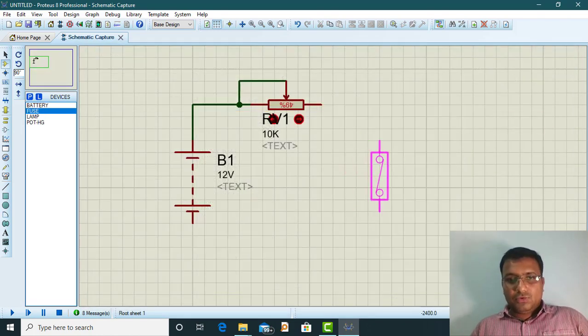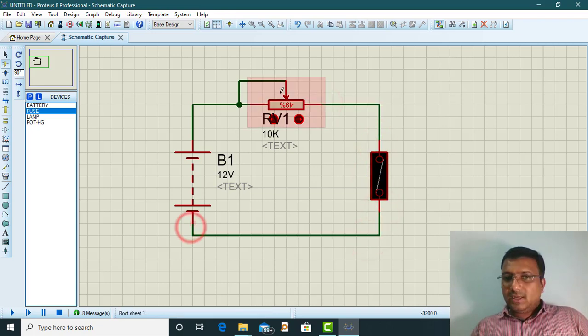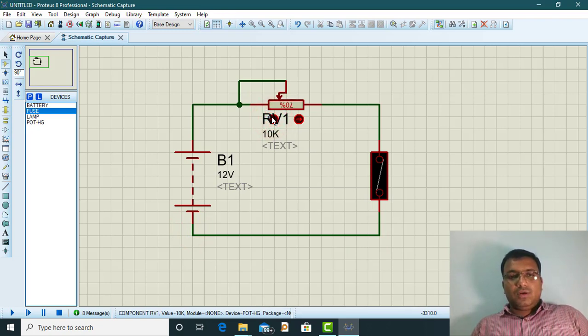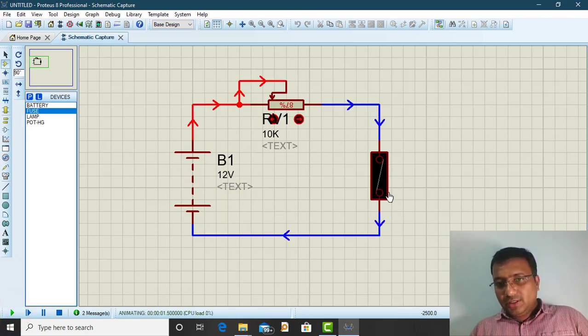Click OK after this and put the fuse here. Okay. So I will keep a fuse. I will connect this in the circuit. Okay, circuit is completed now. I will increase the resistance first. Currently I have a resistance of 87. So I will run it again. For running, I will click here to run this. Once it runs, the fuse is okay. Okay, you observe this particular fuse. I will run it again. So I will decrease the resistance in the circuit.